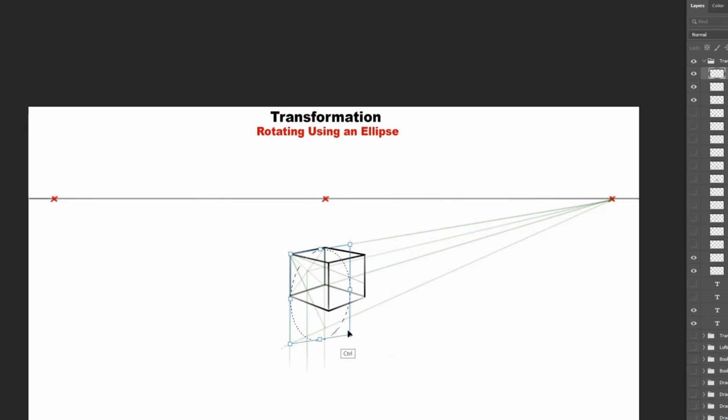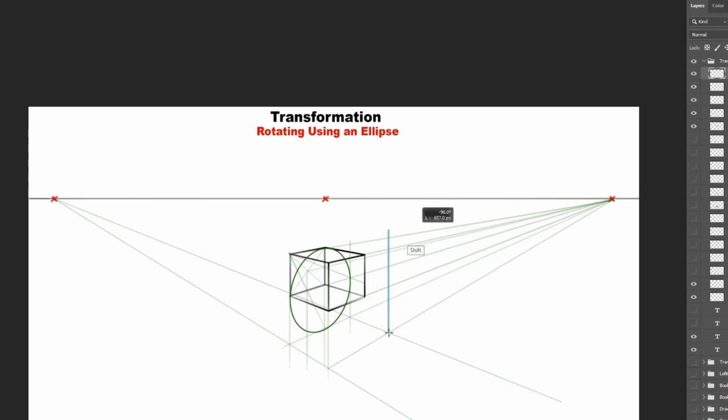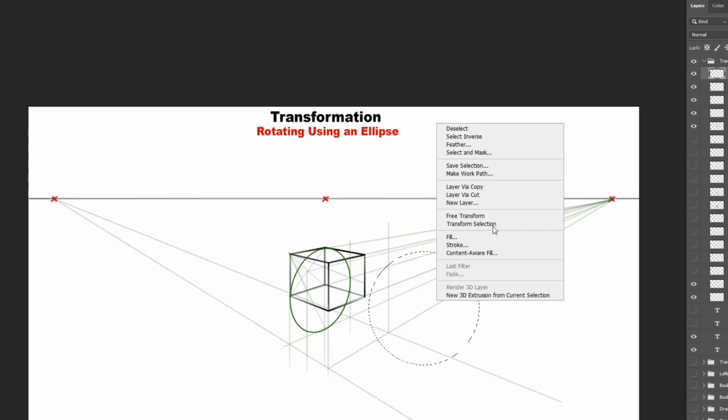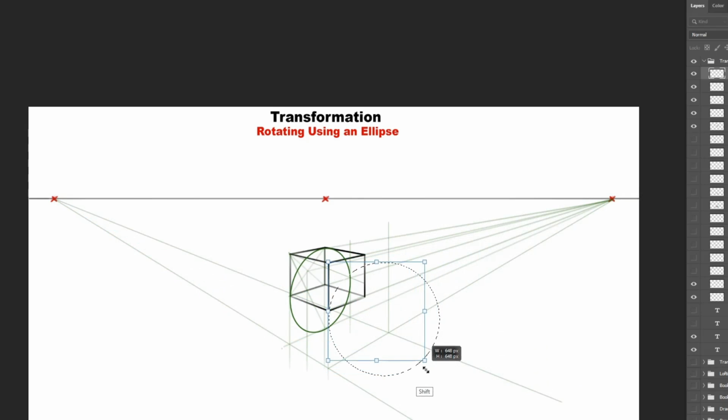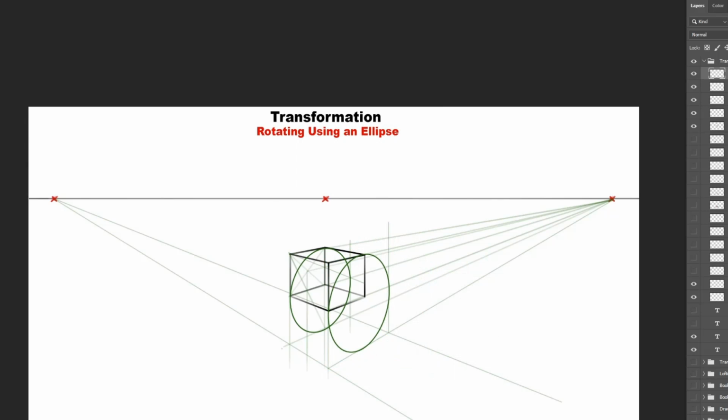Once we have the larger rectangle, we can draw the ellipse inside of it. This time I will draw the second rectangle as well for the right side of the box, or the top side if you consider the left side as the base of the box. So we use the initial larger rectangle to draw the second one and then draw the ellipse inside of it. This way we have two ellipses to draw the box in between. It will make it even more accurate this way.